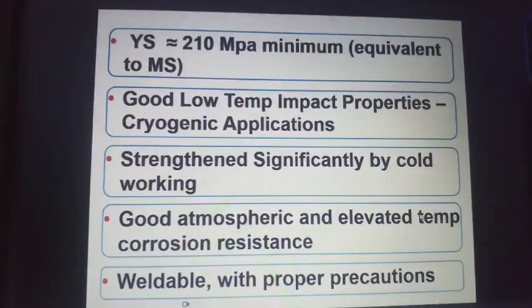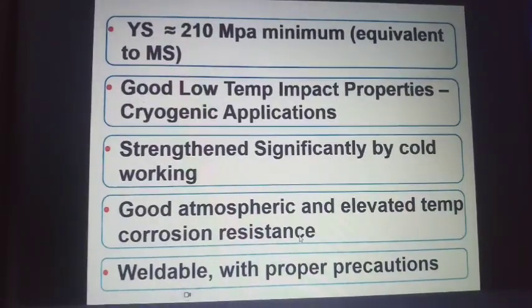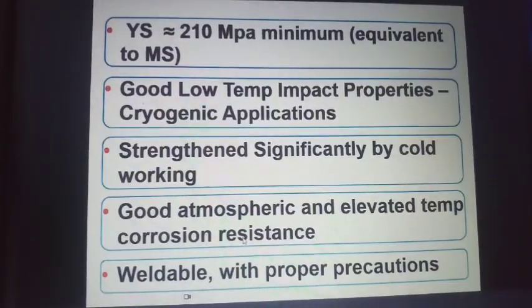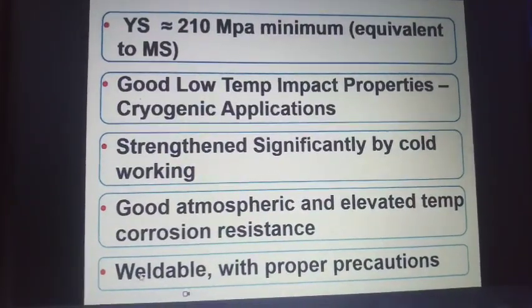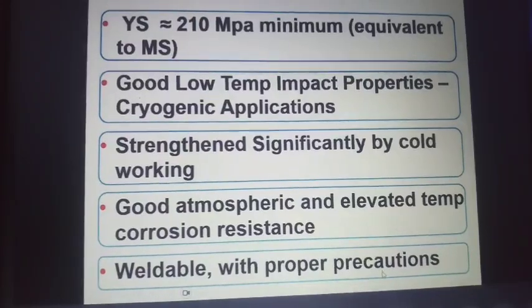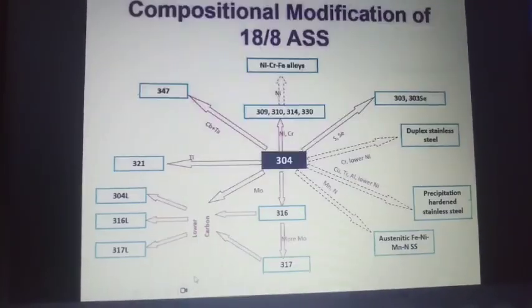Good atmospheric and elevated temperature corrosion resistance. This is because of the amount of chromium and nickel we discussed, 18% chromium, 8% nickel. So we have good corrosion resistance. Weldable with proper precautions. Weldable means we can weld without any cracking or defects with proper precautions.